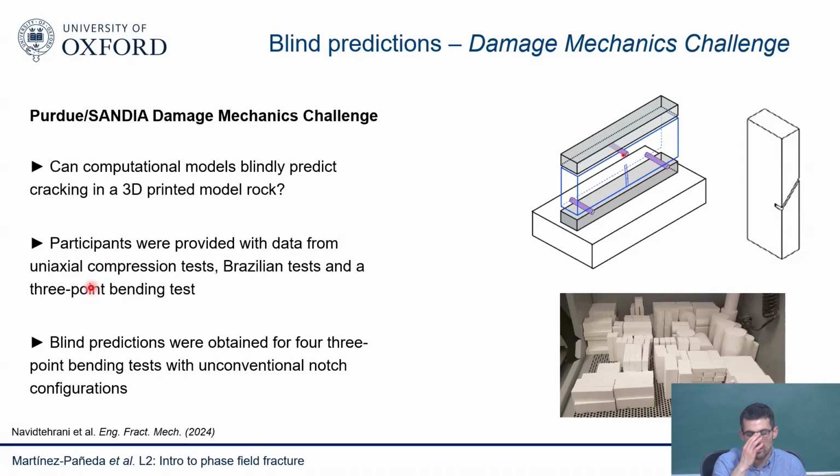And then they'll say, oh, now after that, we'll give you a standard 3-point bending test, a Brazilian test, and a uniaxial compression test. After that, we're going to do tests where we do 3-point bending with cracks placed in different locations, so you get some sort of mixed mode cracking. And we're going to do a 3-point bending test also with a crack tilted. We're going to see how the crack grows in 2D, but we're also going to do XCT scans. And we're going to record force displacement results.